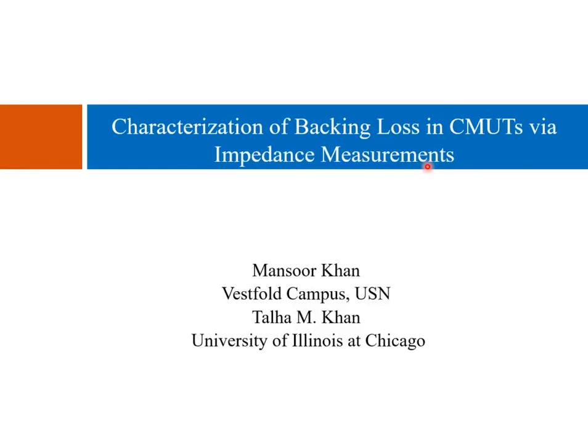In this discussion, I will talk about how the backing loss in CMUTs, which have been produced by anodic wafer bonding technology, include vibrational dampings in their backings, and those appear as baselines in the impedance measurements you take from impedance analyzers. So the baseline that you have in the measured impedance data is very suggestive of the losses in the substrates in the form of pressure or shear waves present in the backing solids.